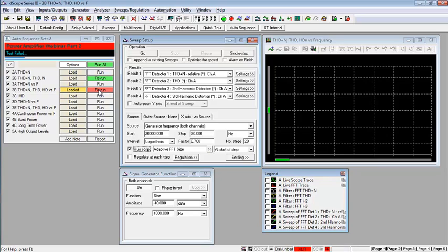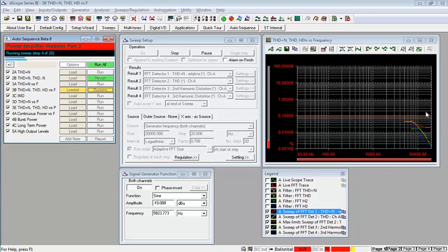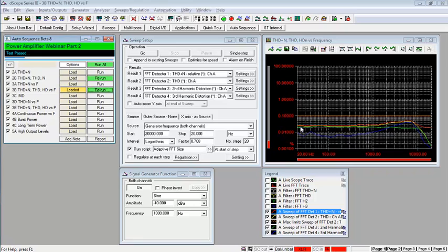So if I now do that, having catered for this low frequency resolution problem, rerun my sweep. We've already dealt with the high frequency issue here. Turn those filters on. And now at low frequency, well, we can see that the sweep is slowing down a little. This is now switching in progressively larger FFT sizes, which are taking longer to execute as this sweep nears the low frequency end. And this sweep is now just about to finish, and well, that's a relief. I've now found all of the problems. This test has now gone green, it has passed, and I've identified what the problems were in my initial analysis.